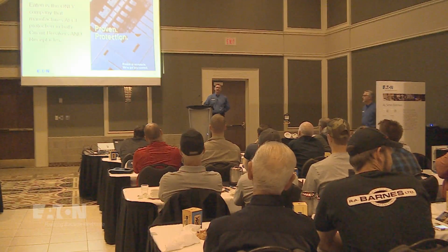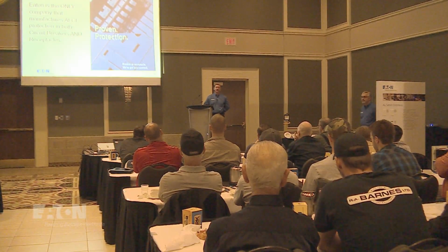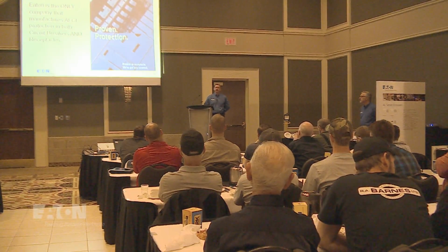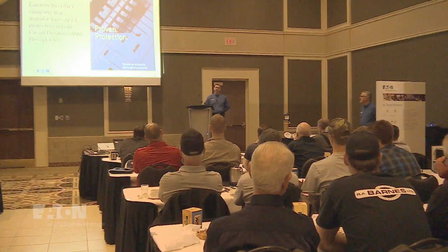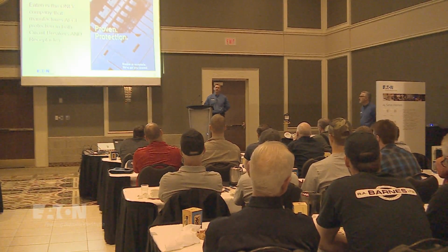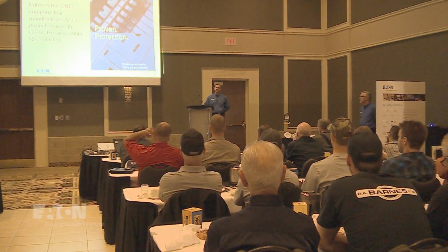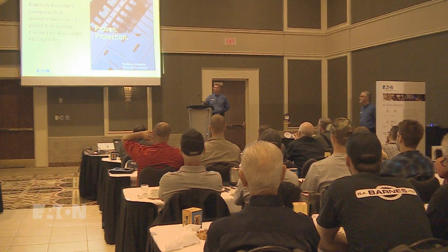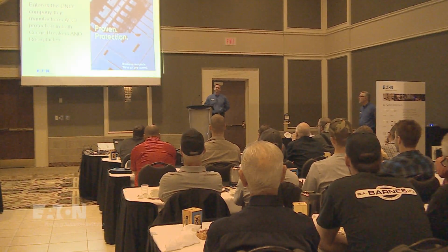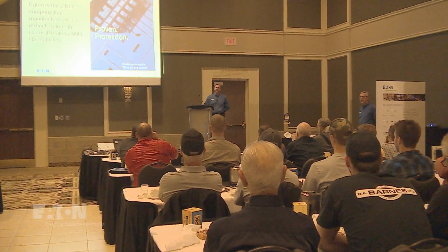So we redesigned the technology in the breakers to look for that as well. It's a continuing process where the engineers are improving this product and the arc signature. So if you get that case where a bedroom circuit is tripping on the vacuum, if you put one of these new combination type AFCIs in, 99% that'll go away.